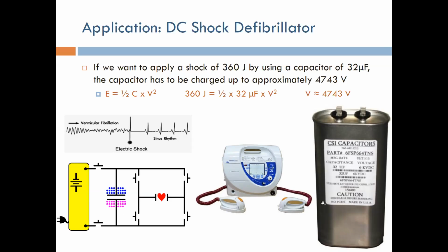So when you're trying to repair that particular capacitor, replace it, or repair any part of the machine, there's usually a way for each one of these devices to discharge the capacitor. You have to do that, and you have to measure the voltage across the capacitor terminals before you touch anything inside the machine. Otherwise, it's going to be a really big problem.